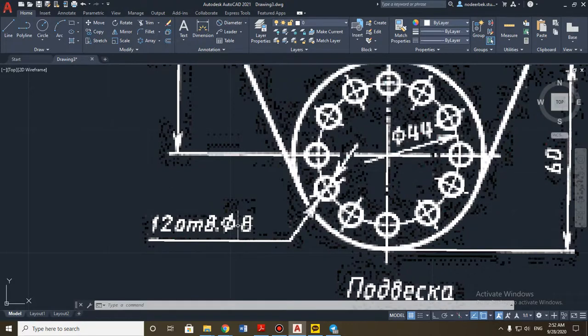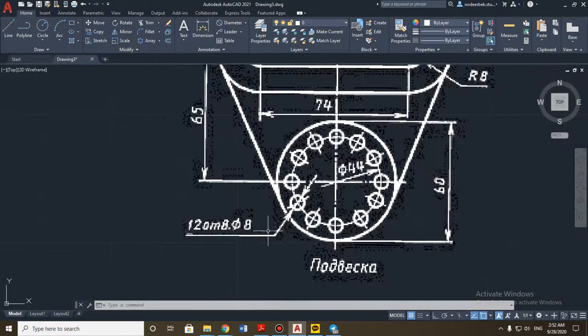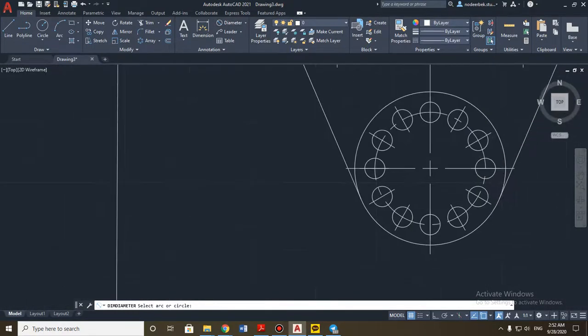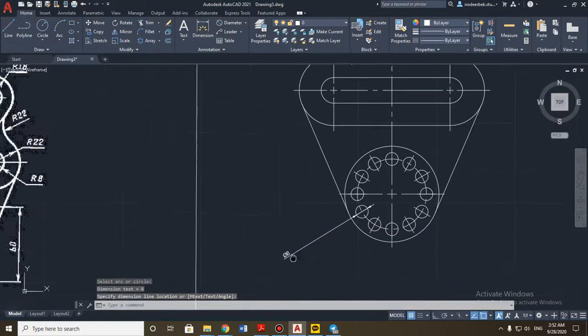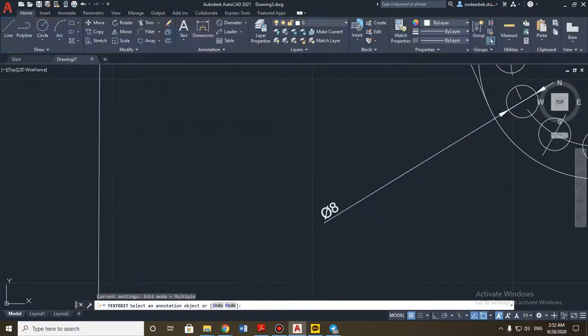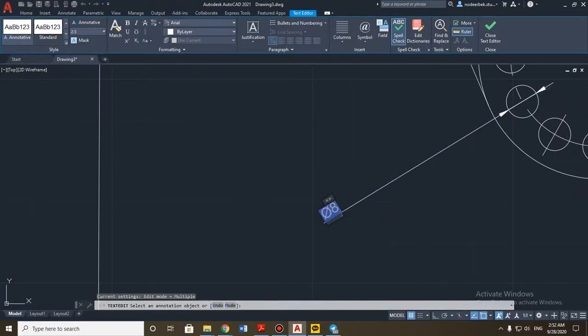before a diameter mark and then the size, there's this kind of stuff. If you want to do this, just use the exact same action. But if you want to put extra text here, just click two times on this dimension and then choose the position, before the dimension or after the dimension.